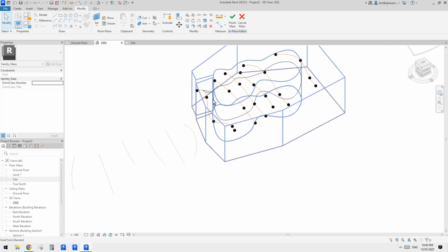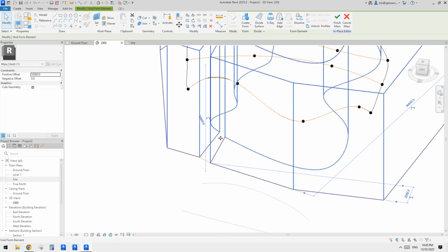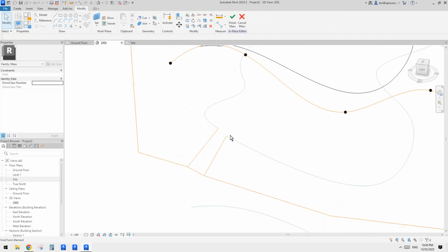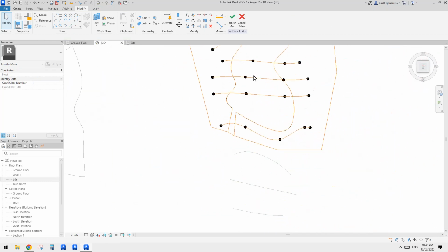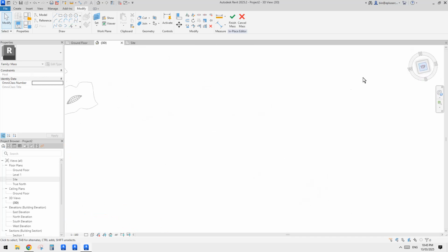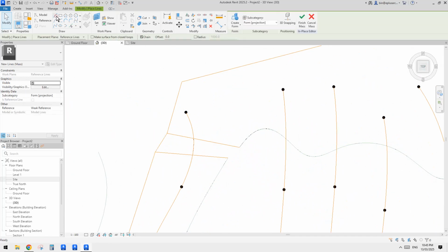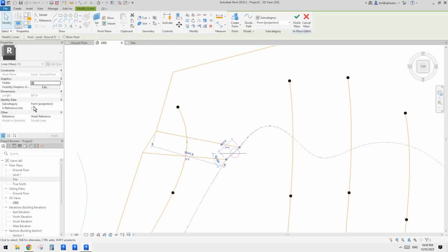We have the void here. Okay, so the second void is actually only this bit, not the whole thing. So we just need to connect this. So let's go to the top view. Still make sure the current work plane is back to ground floor, so we can connect here. Type SE. We need to pick the reference line.